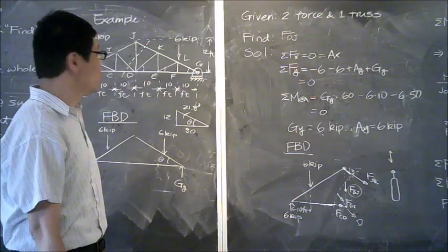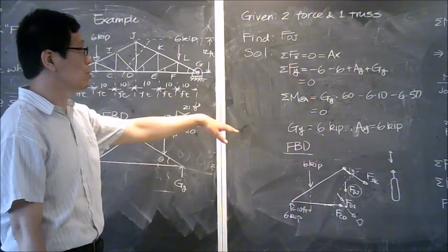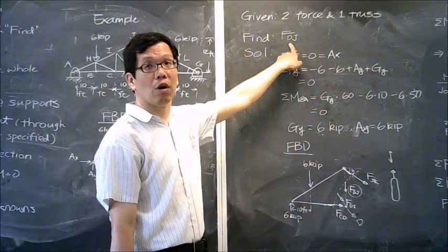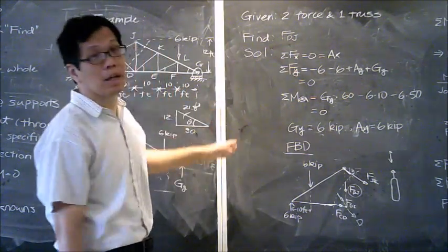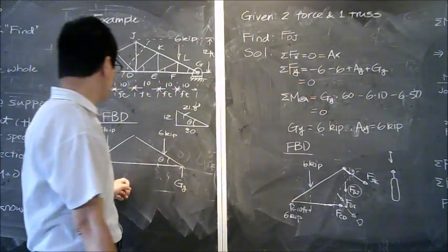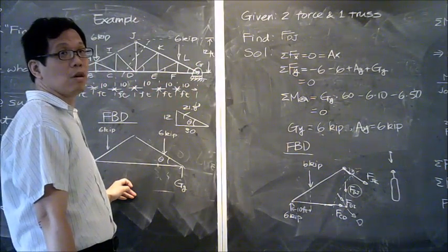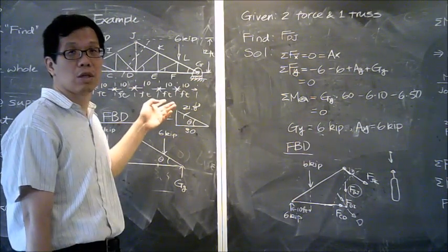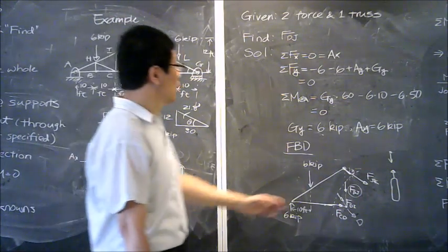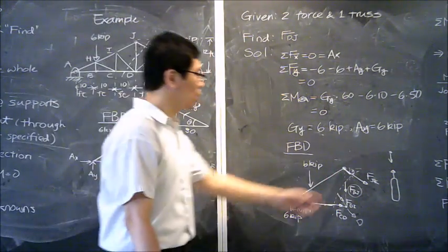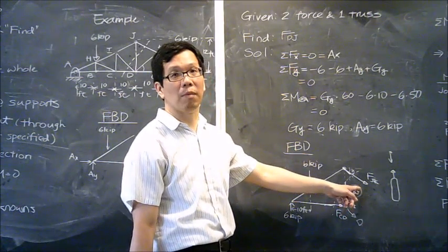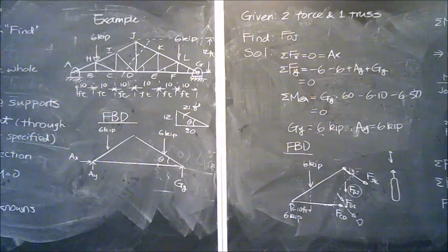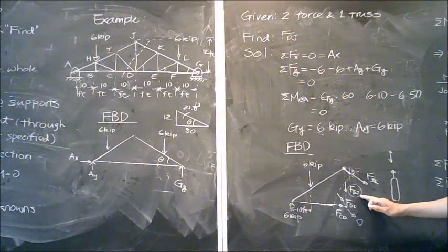So I wouldn't suggest that for these kinds of problems you start right from the method of joints. Specify which member you are interested in, and cut that. If you need some information, start from the beginning, treat the system as a whole. Get the forces of the supports, which are also your external forces. Once you get that down, make a cut. Make sure you cut through the member you are interested in. So when you do that, you eliminate as many unknowns as possible.